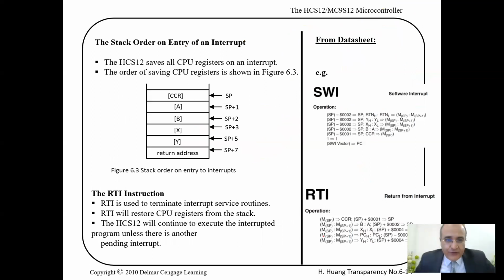And we said we never know when an interrupt comes. So when we covered the subroutines, we only needed to know our return address when we go to a subroutine, right? So what we did, if we needed to use any register and keep its value, we pushed all our registers to the stack. But we cannot do this in the case of interrupts because we don't know when an interrupt is going to come, while we decided when we call a subroutine, right?